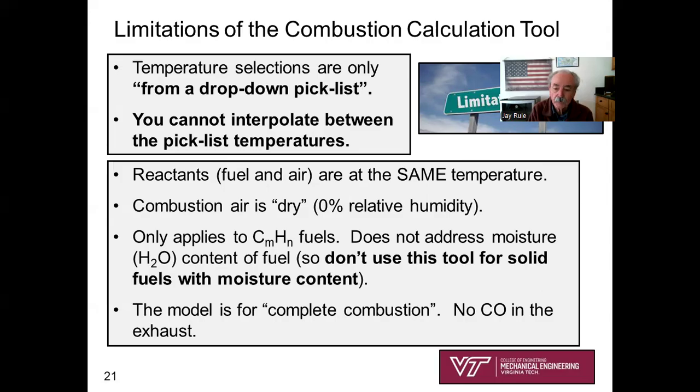The reactants, in other words, the fuel and the air going into the combustion chamber, are at the same temperature. I don't allow for the fuel being at a different temperature than the air. The combustion air is considered to be dry. In other words, we're only dealing with dry air, not air with a certain relative humidity where you'd have the extra effect of H2O vapor in the air to start. Of course, we all recognize that H2O is a natural exhaust product of hydrocarbon fuel combustion.